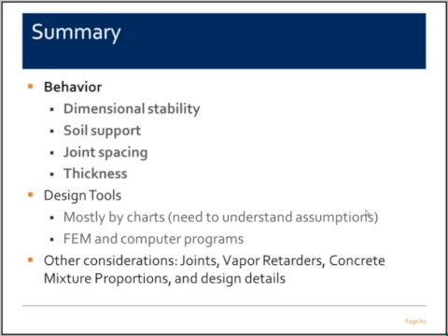Use and loading will often dictate the soil support system and the type and thickness of slab to be used in a particular project. Koray did go through some design tools. These design tools are available through PCA and in ACI 360 as well. And we should keep in the back of our mind that we have other tools available to us as well, finite element modeling and other computer programs. There are quite a few other considerations we need to think about when we're troubleshooting slabs on ground. Those include joints, vapor retarders, concrete mixture proportions, and design details.